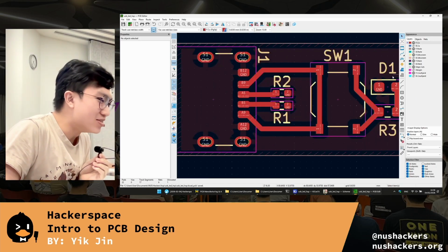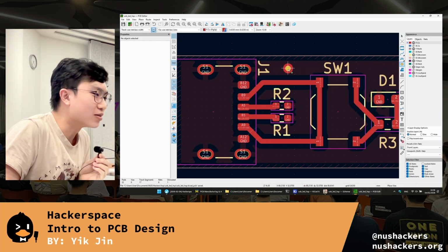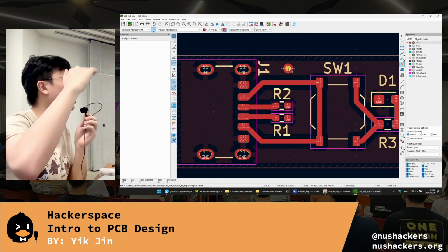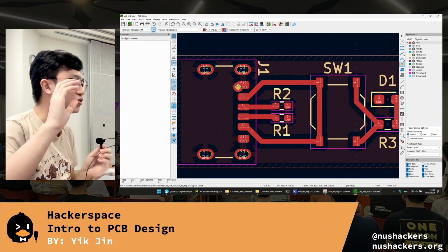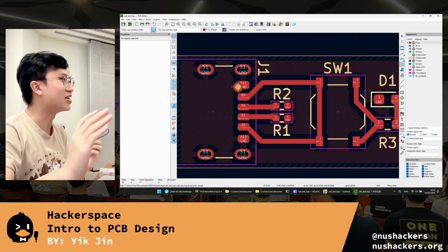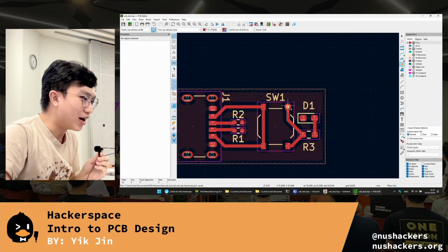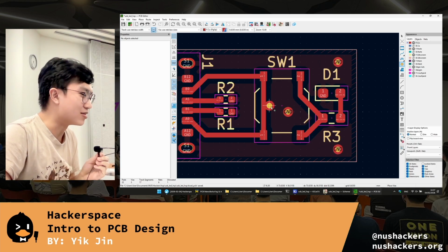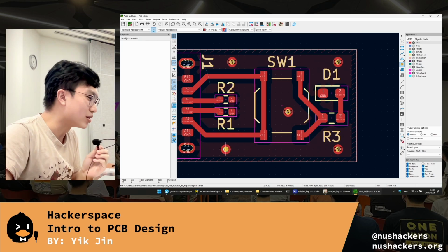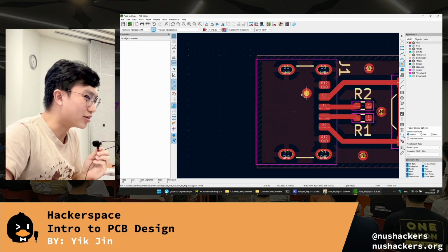How do you do that? Very easy. You put what we call vias everywhere. A via is the thing that connects the top and the bottom layer. Because your top is ground and your bottom is ground, just connect them together. If you put enough connections, they should eventually all connect to the same ground. I usually like to put quite a bit of vias because it's good PCB practice, and it also gives me less trouble afterwards with errors, which I will show you later.